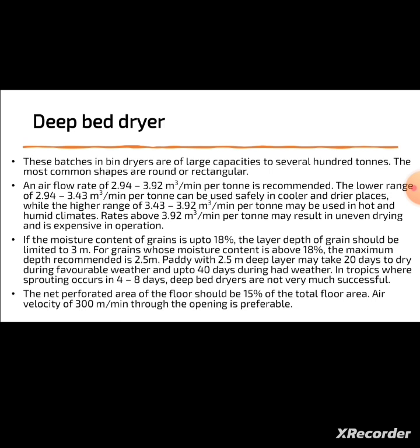than 20 centimeter, and different airflow rates are recommended based on the surrounding area, surrounding temperature, as well as the product. So if the moisture content is up to 80%, the layer depth should be limited to 3 meter. For grains whose moisture content is above 18%, the depth will be 2.5. So paddy with a 2.5 meter deep layer may take 20 days to dry during favorable weather conditions. So these are some of the deep bed dryer details.